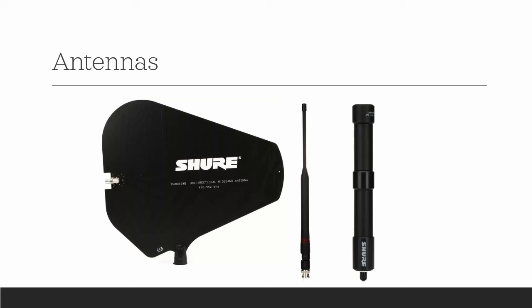If we move to the right, the larger dipole antenna is just a wide bandwidth antenna. The length of the antenna generally corresponds with either a quarter wavelength or half wavelength of the frequencies you're trying to pick up. The bigger antenna covers a much wider spectrum. So if you're going to do very dense deployments across the full spectrum, and I say that's a pretty loaded statement, where you're using more than a handful of bands, combining into a single system is the best way to do it. That would be the best antenna to use.